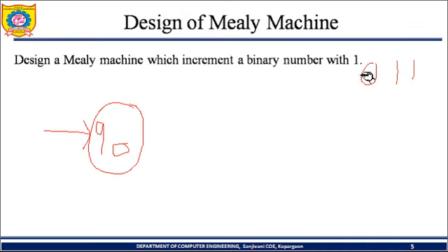Let us consider this one is the string, so I am going to scan the given string from this side. So 1 is there, so for 1, which logic we have decided, we have to invert the bit up to what, up to 0. So if it having 1 input, so we have to invert the bit, means 1 will become 0 and we will be in the same state.